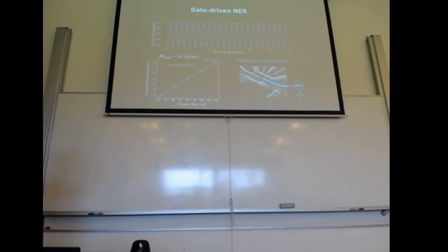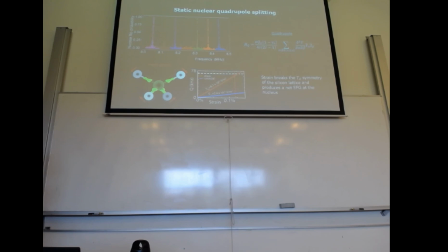All right, now if that idea is correct, at that point we hadn't imaged the device yet, but if that idea is correct, we don't need this microwave antenna at all to drive a nuclear spin. We can just use one of the many gates that we have in the device and hook our signal generator up to that gate. So that is what we did. And then, of course, we could get beautiful Rabis, etc., also using this gate. Okay? So this is for one of the transitions. All right? So that confirmed that picture to us.